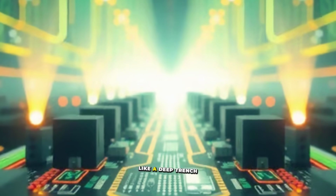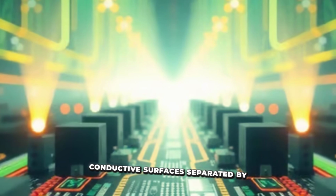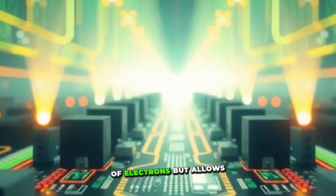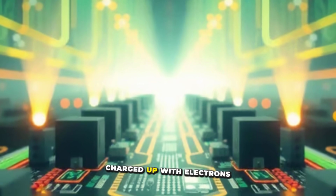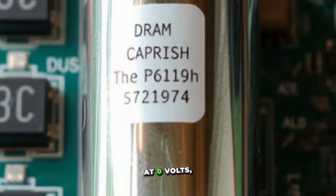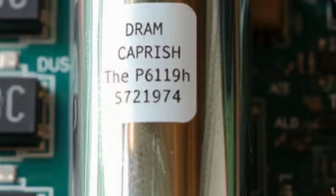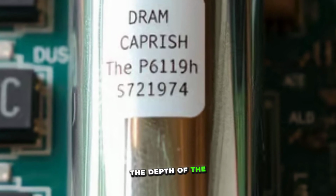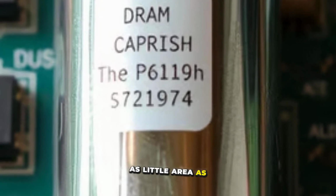The capacitor is shaped like a deep trench dug into silicon and is composed of two conductive surfaces separated by a dielectric insulator or barrier just a few atoms thick, which stops the flow of electrons but allows electric fields to pass through. If this capacitor is charged up with electrons to 1 volt, it's a binary 1. And if no charges are present and it's at 0 volts, it's a binary 0. And thus this cell only holds 1 bit of data. Designs of capacitors are constantly evolving, but in this trench capacitor, the depth of the silicon is utilized to allow for larger capacitive storage while taking up as little area as possible.